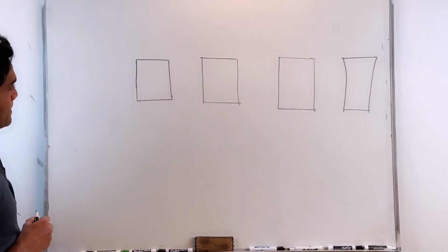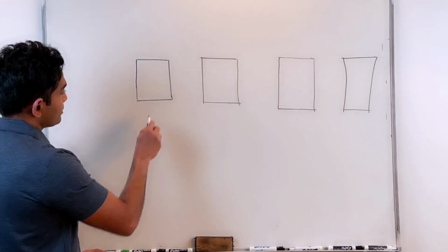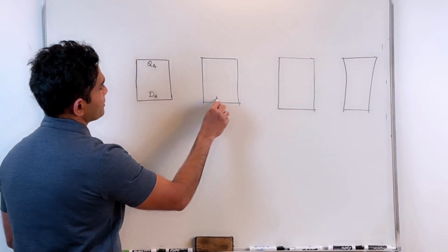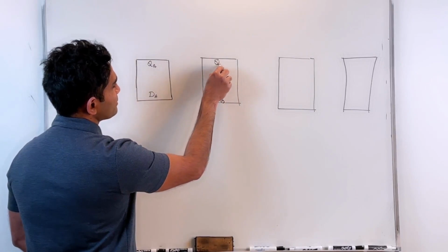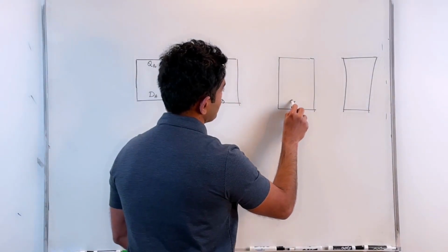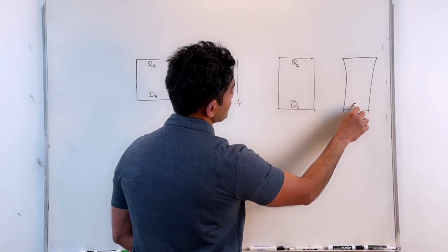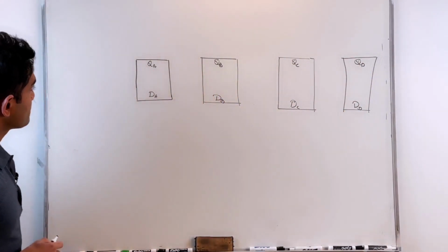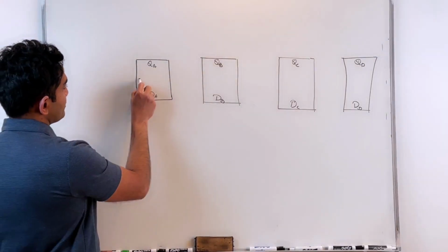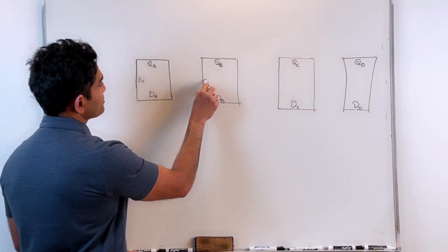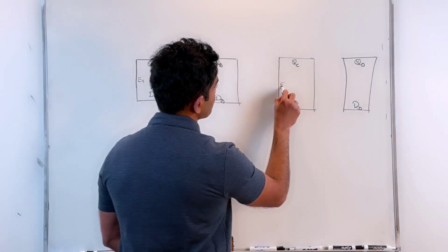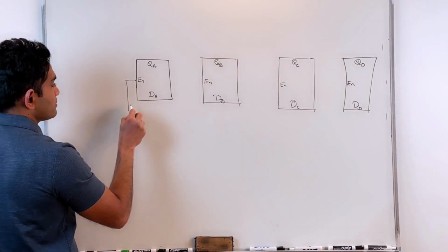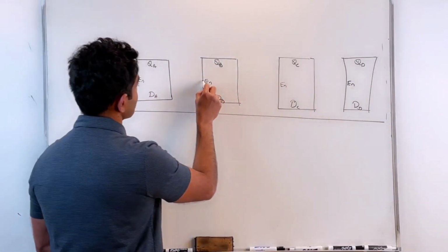And we call these DA, QA, DB, QB, DC, QC, DD, QD. And these are the enable inputs for this flip-flop, which are connected to the clock. All of them are connected to the master clock, so everything is synchronized with the master clock.